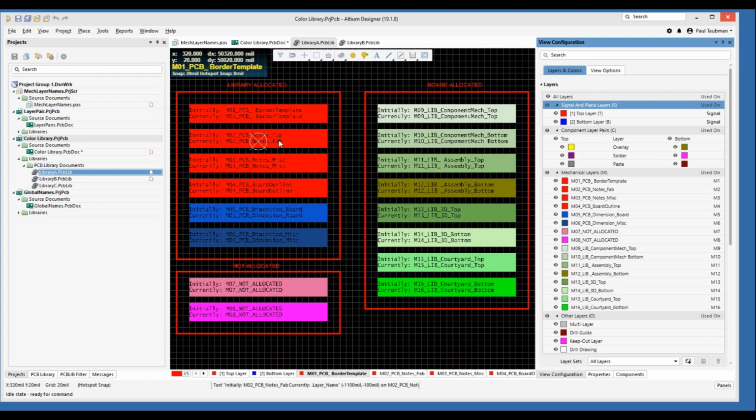If you're working in the libraries, you're working in the design, you wouldn't probably be operating this way, so this would not be obvious to you. You'd probably change a color, and then later on you open it up and you say, well, why did that color change? I didn't change it in this layer. Well, it did get changed, it just didn't happen until you actually refreshed it, and that seems to be done by doing a close and reopen. So how do we control the colors here?